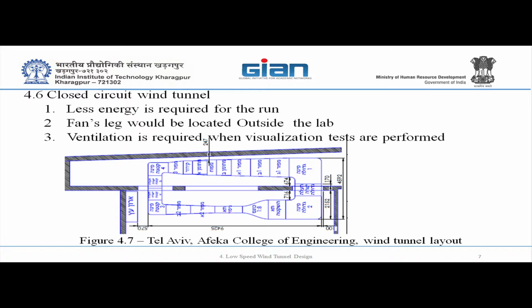Don't forget, keep those sections removable. We'll talk about the turning vanes. Even turning vanes, you would like them to be removable, so you can take care of them. Sometimes you want to replace them. I didn't mention here the heat exchanging on a closed circuit. Most likely you will need to cool the air, because if you run a long time, the energy is heating it up.